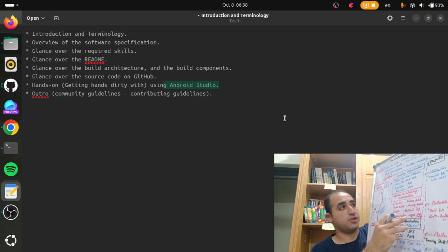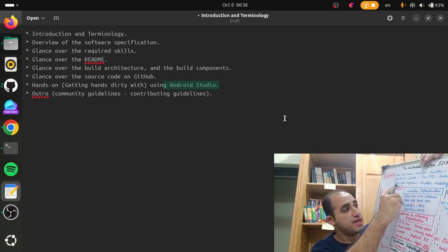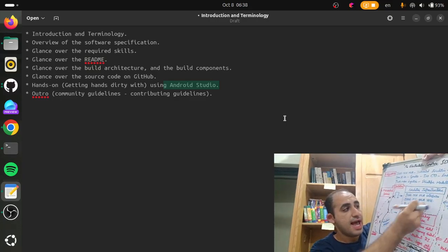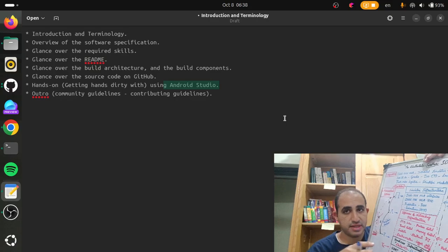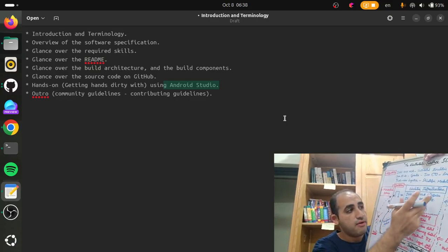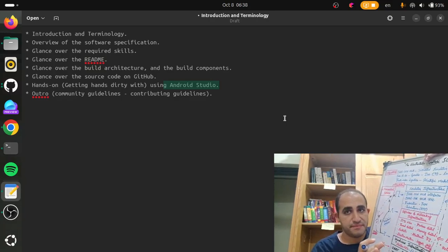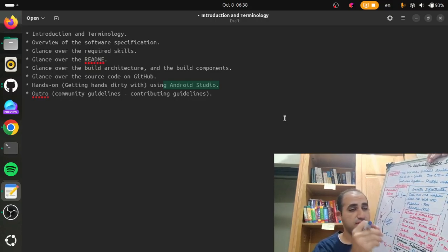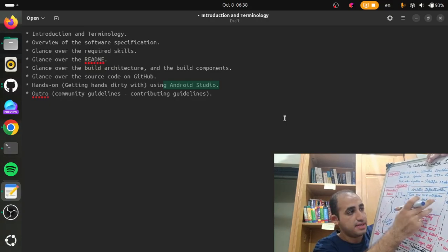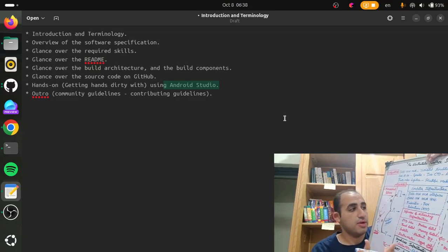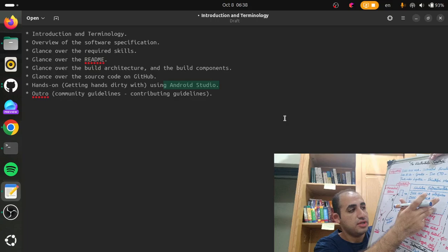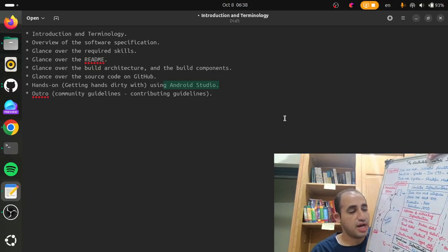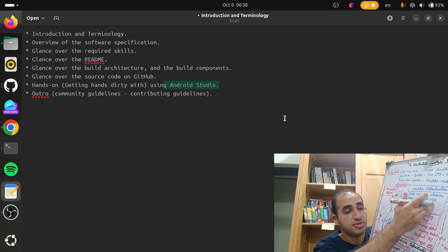We get to the simulation infrastructure first. That is the interfaces of the IEEE HLA and the RTI, the runtime infrastructure. And it is composed of federates, that's the devices that you want to connect together. The FOM, the Federation Object Model, that's a standardization for the data structures to transfer or to encode from device to device, to encode in the transmission protocol, all right? And that is the federation, which is the RTI. So the host starts the federation or the RTI, and the other devices connect to this RTI and initialize, and connection starts, and then transmission starts by FOM.